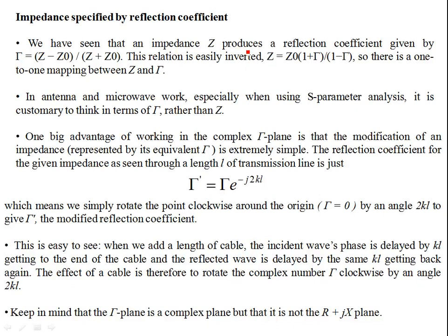that if a transmission line is terminated in its own characteristic impedance, then it produces no reflection. Okay, so if you have a scenario like this, what we talked about before, a transmission line, if it is a parallel plate conductor or coax, whatever it is, if it has a natural impedance which is given by Z naught, which is square root of L over C, if it is terminated into its own characteristic impedance, or if it is infinitely long, let's say ZL is Z naught, in both cases you don't have any reflection.